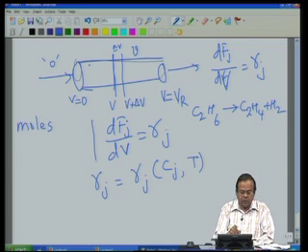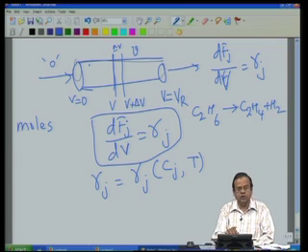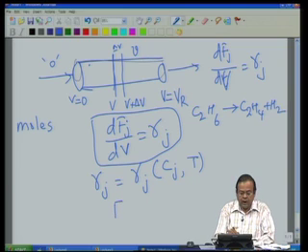This mass balance equation does not have concentration in it. Remember, the mass balance is on mass, that is on moles. So, how do we now relate these two? So, we know by our definition Fj divided by volumetric flow rate is our concentration Cj.